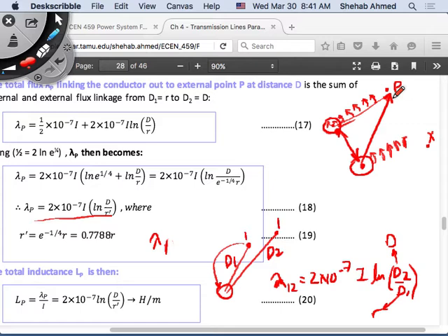That tells me the effect of this conductor on the flux. Flux patterns add vectorially. So I have all the flux between these 2 points, which is linking this conductor due to itself. But then I also have all the flux between the same 2 points, and I add them to this existing flux that was due to this conductor alone.